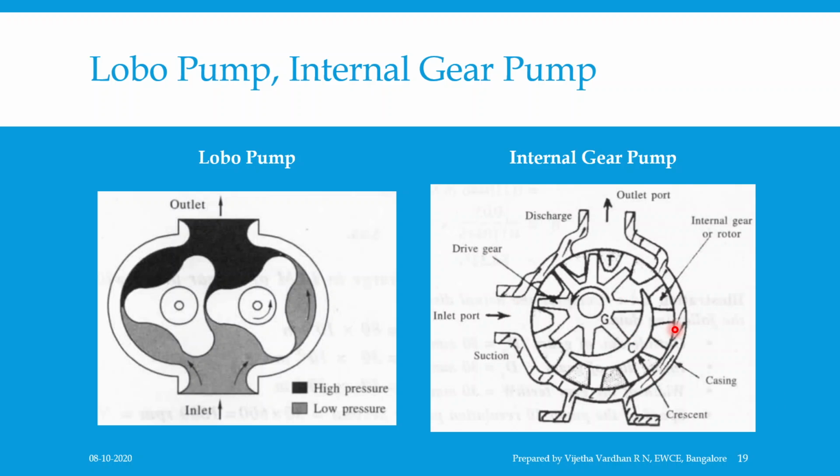Then one more concept is called reversing of input shaft rotation. How is it going to be achieved? Let us understand it. In some internal gear pumps, the annular wheel, which is called the internal gear, which you can observe in the figure, is driven with the external gear connected to the drive shaft. But in some types, the external gear is driven while the internal gear is connected to the drive shaft. When the external gear is the driven gear, by rotating the crescent seal and the internal gear assembly by 180 degrees, the shaft input rotation may be reversed.